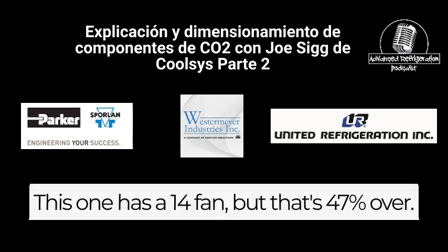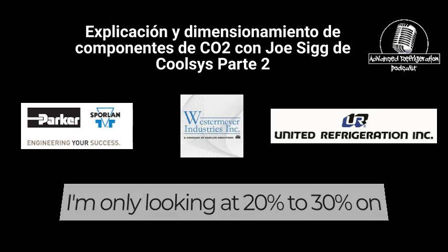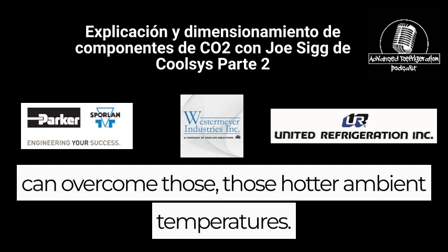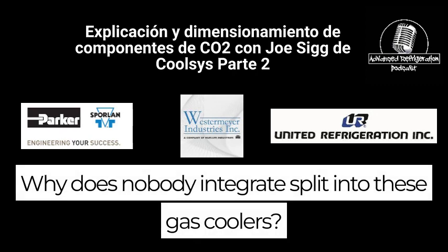If I look at this one, that's a 14 fan, but that's 47% over. So I don't need that much. I'm only looking at 20 to 30% on my gas cooler, so we can overcome those hotter ambient temperatures. Gotcha. Here's what I would ask you, Joe. Why does nobody integrate a split into these gas coolers?